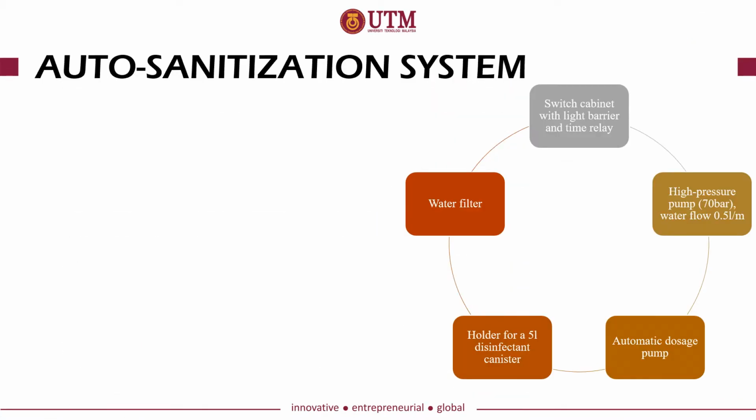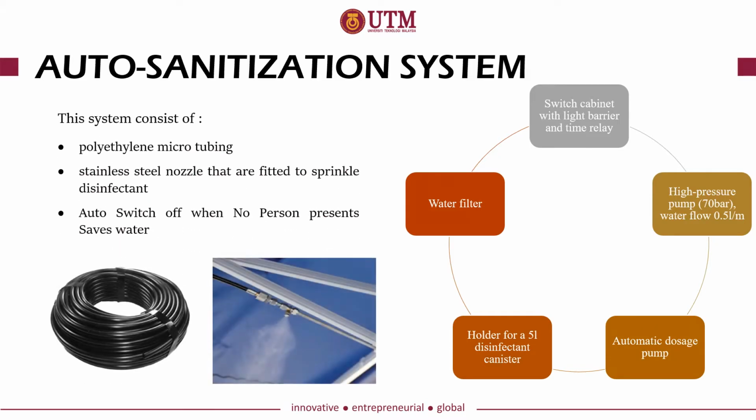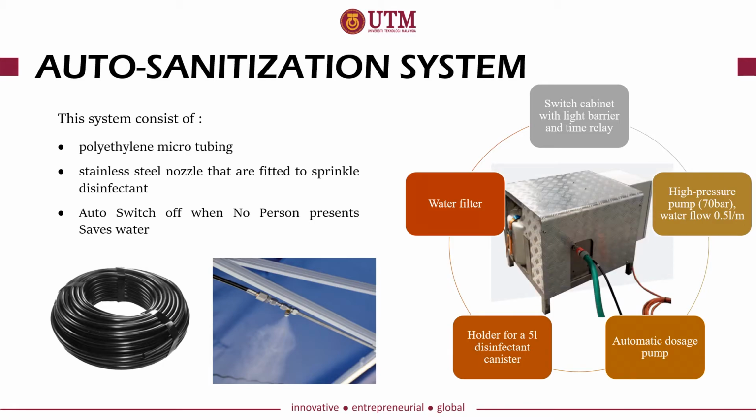Lastly, the auto sanitization system. This system consists of polyethylene microtubing and stainless steel nozzles that are fitted to sprinkle the mist of disinfectant, and it automatically switches off when the sensor detects no one. And here is the pump box, which consists of a switch cabinet with light barrier and time relay, water filter, high pressure pump, disinfectant canister, and automatic dosage pump.